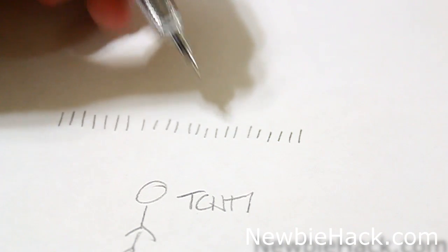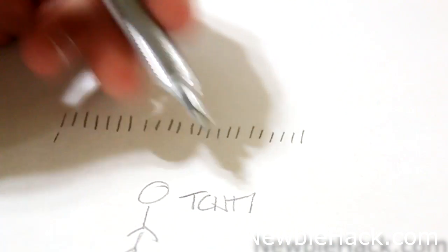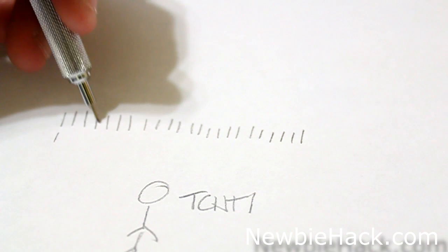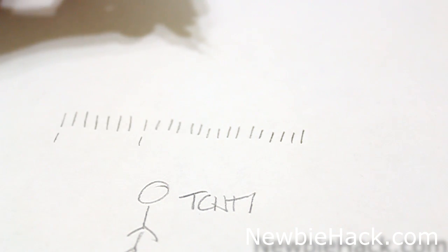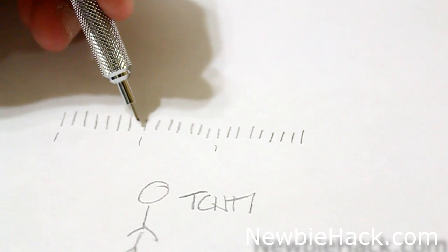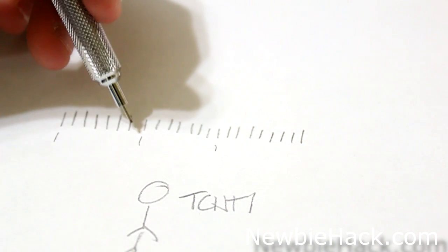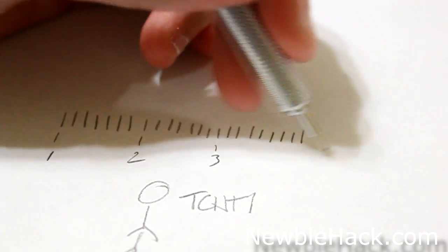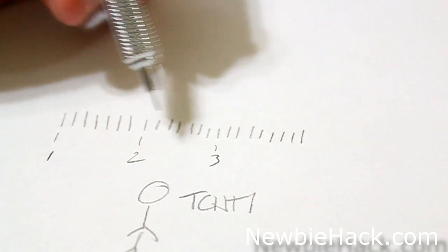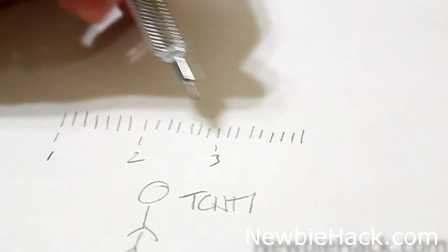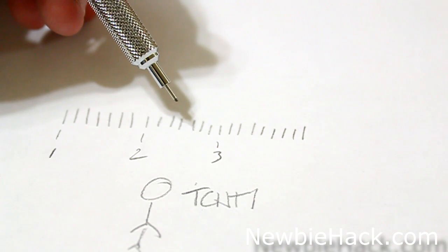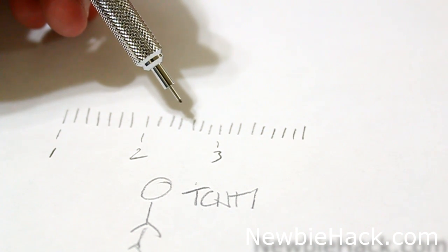If it has pre-scaling of, let's say, 8, Mr. TCNT1 only counts when the internal clock has ticked 8 times. So let's see, 1, 2, 3, 4, 5, 6, 7, 8. So it'll count again here. 1, 2, 3, 4, 5, 6, 7, 8. It'll count again here. So every time the internal clock ticks, if it's pre-scaling of 8, it'll have 1 here, 2 here, 3 here, and so on. And that's the same thing as the pre-scaling of 64 or 256 or 1024. What that does is it slows down the TCNT1 enough so it's more compatible with the scale of the clock that we're essentially used to.